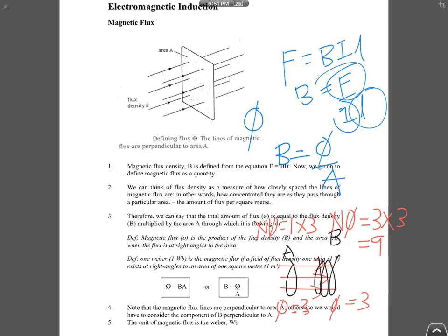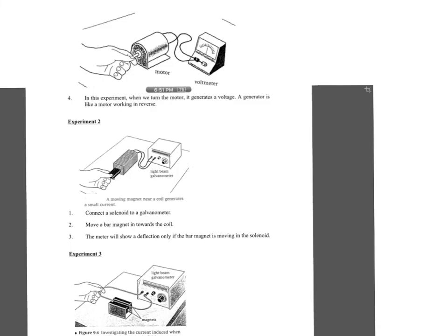The formula for flux, which I gave you just now, is flux equals BA. So flux linkage, with N phi as the symbol, equals NBA. Do not cancel the 2 N's here, then you won't get flux linkage. The symbol is N phi, so therefore the flux linkage is NBA. The unit is also Weber. Alright, so this is what you mean by flux and flux linkage.